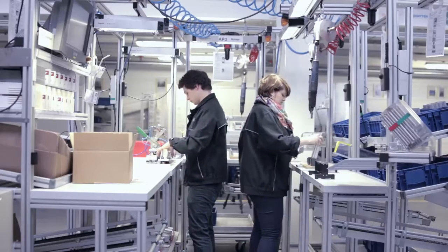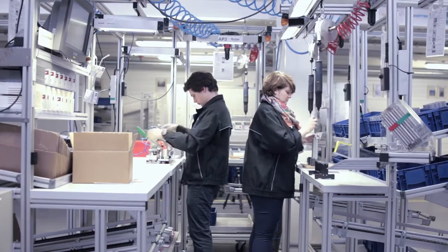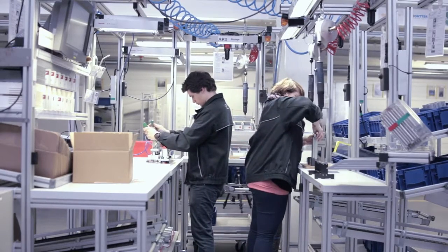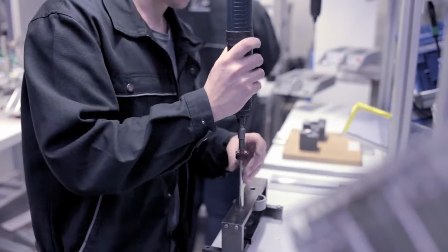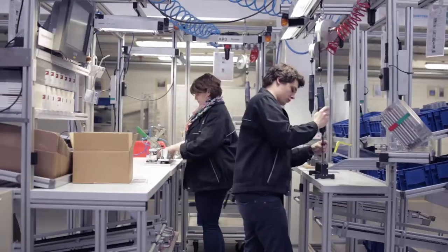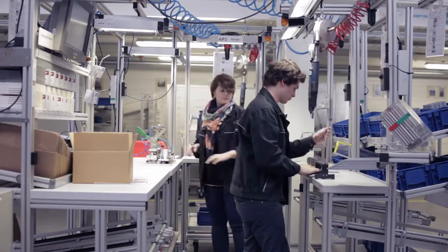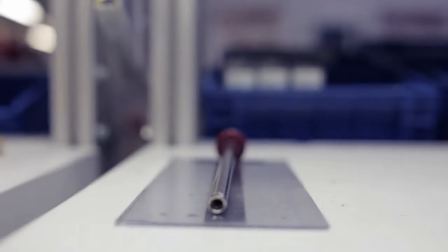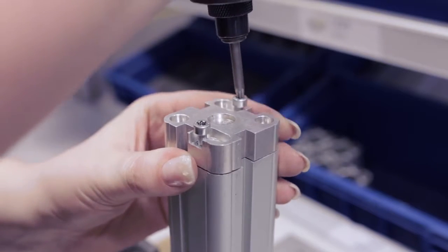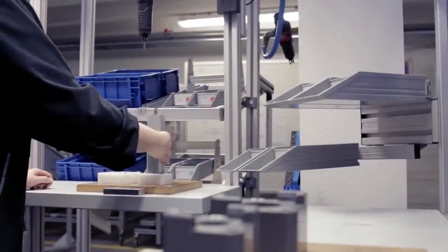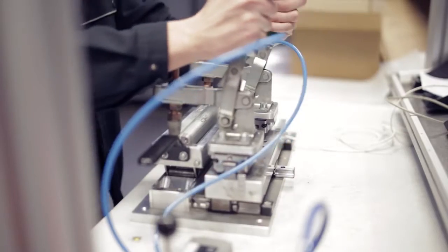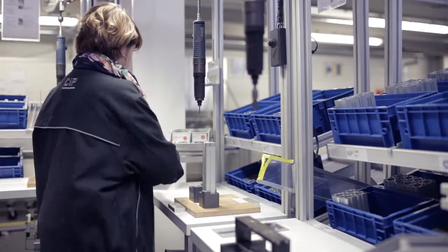If the newly designed work system is now started up, the effects of the changes are immediately and clearly evident. The material is staged ready for use and as close as possible to the place of consumption, which effectively helps to reduce non-productive times within the assembly process, for example, for searching and unpacking parts. The reduction of the batch size to just one piece, combined with an even balancing of the working steps, means that components are further processed directly and no intermediate stocks pile up between the individual stations.